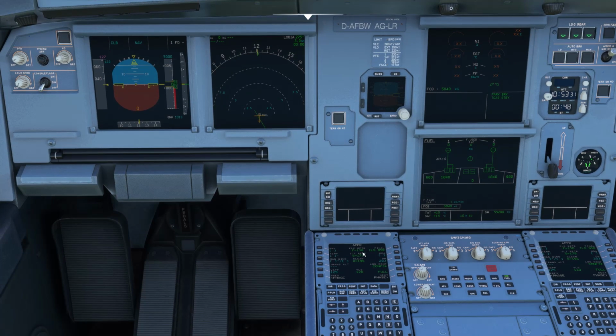Okay, so as I've got that entered at 283, when we are into the approach phase, basically what will happen, it'll display 283 somewhere there, and then it'll sort of count me down, and it'll tell me when I'm 100 above, and then it will tell me when I'm at the minimum. And then at that point, when you hear minimum, if you can't see the runway, that's when you need to think about going around. I think that's roughly the idea of it. Decision height and MDA.